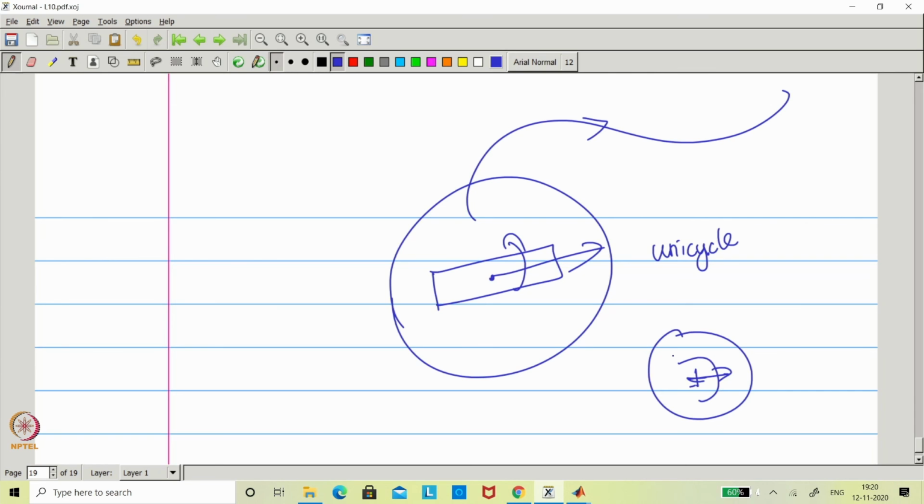Okay. So this is lecture 10, where part 3 is also done. What we have seen in lecture 10 overall, from part 1, part 2 and part 3, is all the kinematic simulation. Why is this kinematic simulation important? You might already know: it shows how the individual parameters play in the overall performance. That is what you call simulating or analyzing the system, right? Now, say you take the wheel size as given in the catalog, but you are not getting the required longitudinal velocity. Then you can go to another wheel, or change your motor. In that sense you are coming into a design aspect. So this is what is important.